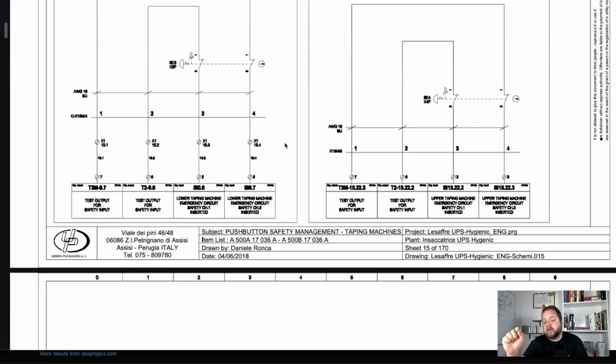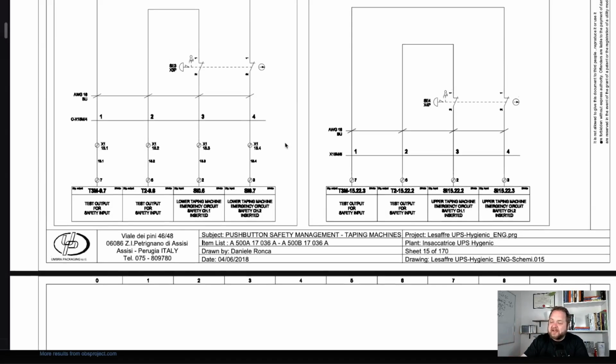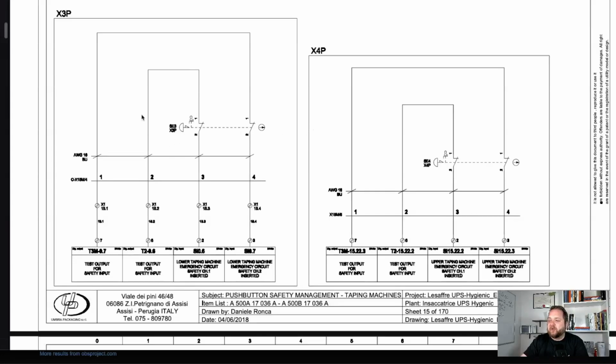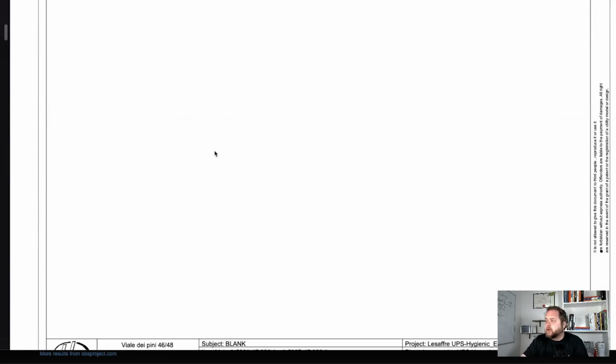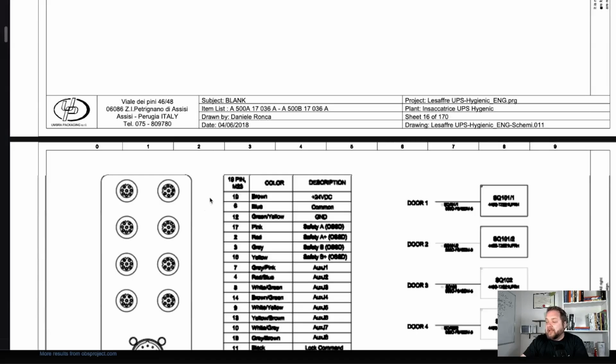If you bring in a machine that is going to miswire some of these circuits, and I've seen all sorts of different things. For example, it goes through the e-stop and then this wire comes out and comes back into the second terminal and then basically hits both channels that way. That is not proper safety. So you want to make sure that some of your engineers or even managers review these drawings and understand what is going to be placed in the field.